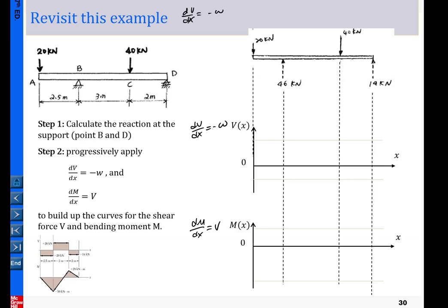For these questions, we still want to construct the shear diagram and bending moment diagram. We start from the beginning here. The 20 here is our sign, positive shear. In this case, you can see this is a face left, and we have the 20 downward. Per our sign convention, that is negative. So starting from here is negative 20, corresponding to the load here.